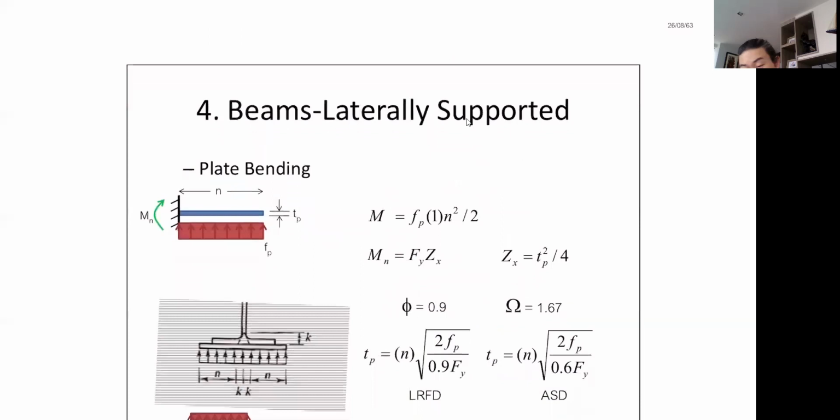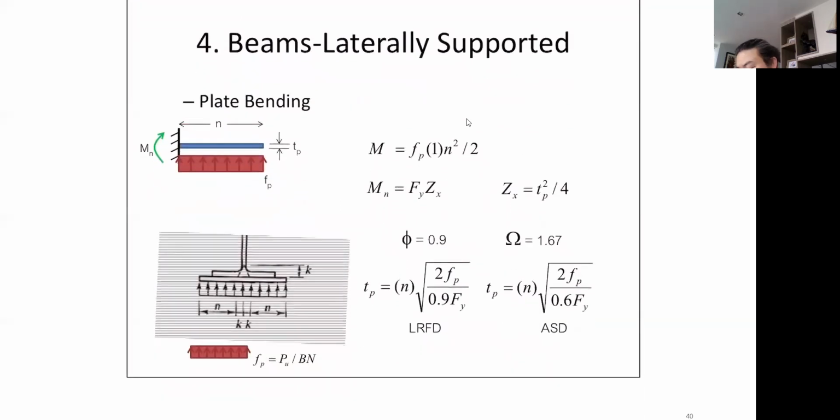All right, and plate bending, last one. Now remember, we have the design model. Now we can calculate your moment. This is based on 1 unit of your plate width, okay? So let's say your plate is long in whatever direction you may have. We can design this plate by assuming that the width is 1 unit, and you can design the strip of 1 unit here.